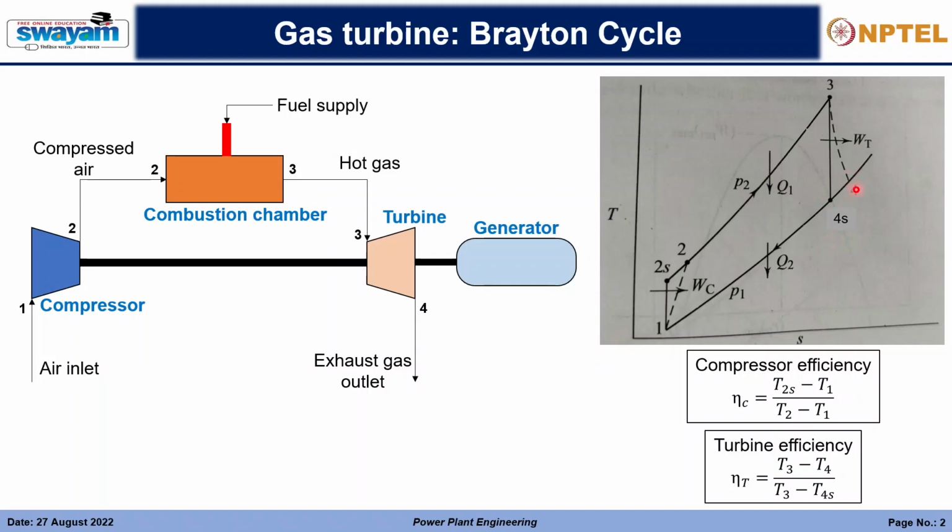So here at this particular temperature, you can see that the difference between the highest temperature, the inlet temperature, and the final temperature has decreased. So the work done inside the turbine also now decreases. Then from point 4, the hot flue gas exits the turbine, as you can see here. From point 4 it exits to the ambient, where the gases lose the heat.